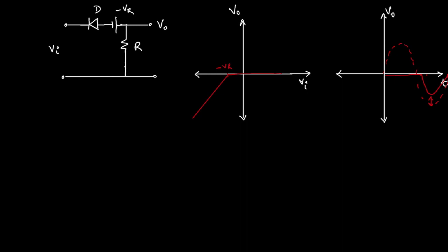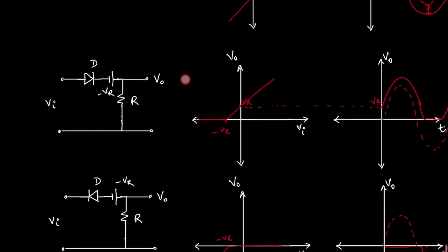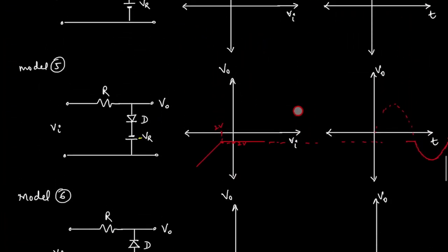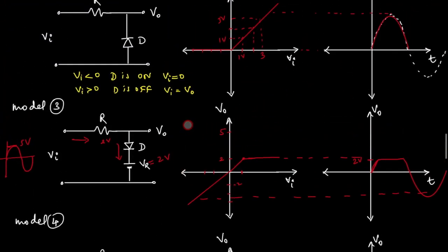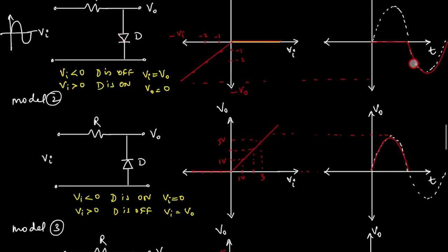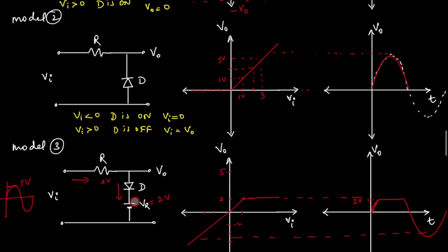And now next we'll take two level clipping, two independent level clipping. There are again four models which are very easy. There are tricks, based on what we have learned. We have learned on shunt, right? So we have got some output. So what is the trick here? Let me show. If the diode is downwards, it means you'll get the downward signal. If its position is upwards, you'll get the upward signal.